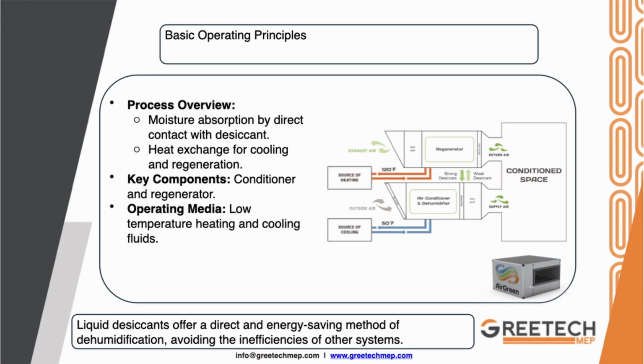50% of the applications are in process plants, food, beverage, chemical, petrochemical, and other industrial processes, where you can get a line of chilled water at 50 degrees Fahrenheit that would feed the conditioner. Likewise, you can take advantage of the waste heat of the processes with a plate heat exchanger to obtain water at 120 degrees Fahrenheit. Waste heat is abundant in process plants of this type.